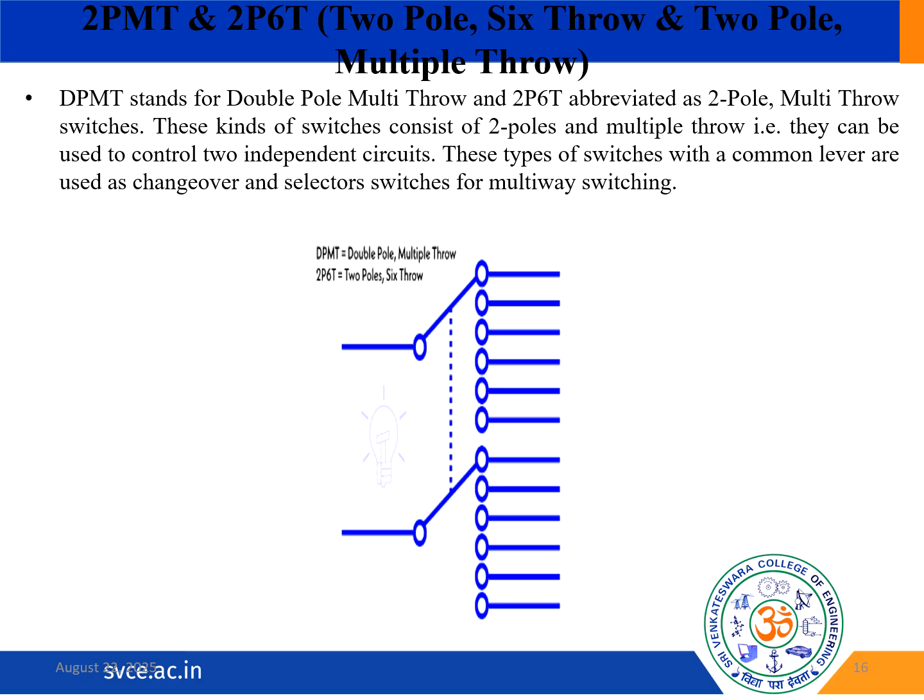So these switches are versatile and can be used for electrical components designed to manage two independent circuits simultaneously. The pole represents the separate circuit path, while the multi-throw aspect allows each pole to connect to multiple output terminals. These switches typically feature a single lever or actuator that controls both poles in unison, and it makes them ideal for changeover operations.